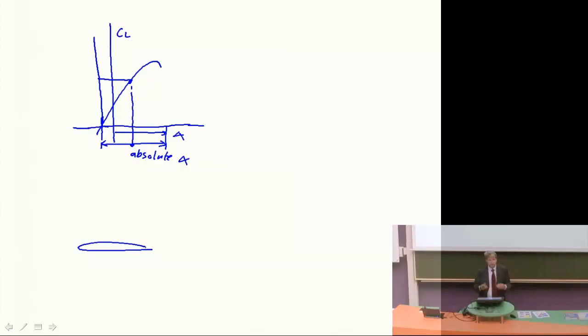and understanding basically that the lift force at the wing is the result of the difference between two giant forces. Remember that we saw the air pressure, that's a huge force, and there's only a minimal difference required of a few percent between the top and the bottom side of the wing to get this lift. But if you get those two huge forces on the downside and the upside of the wing, if they differ a bit, they probably also differ a bit in the point where they apply. If you sum all the pressure differences along the surface, you get a huge force. And so imagine that the lift force is a bit to the back.